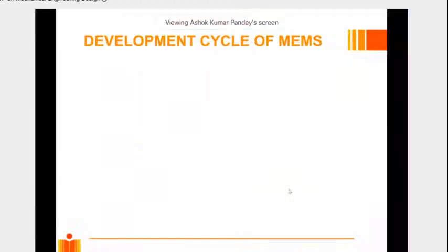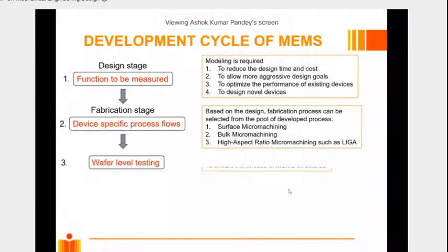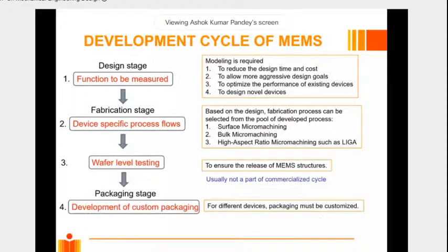Yes. So that's what I discussed, that first we need to decide what we are going to fabricate for. Whether you are going to use MEMS as a mass sensor, temperature sensor, or pressure sensor, and based on that, you will have to decide how small a change you want to measure. After you decide it, you correlate it with the corresponding frequency, and based on that, you can fabricate your device. So that's how we design it and then fabricate it, and we do testing, and that's how basically it goes on.